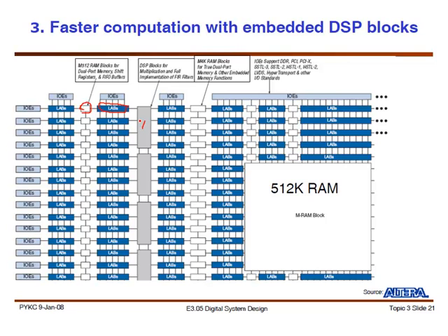These would be the DSP blocks doing multiplication and so on, and you can see that there is a big mega RAM block, 512K RAM, and again you can see the heterogeneity of the structure, and one thing that is similar to what Xilinx had. Remember, Xilinx arranged all the block RAMs into one column. Same thing is happening here.